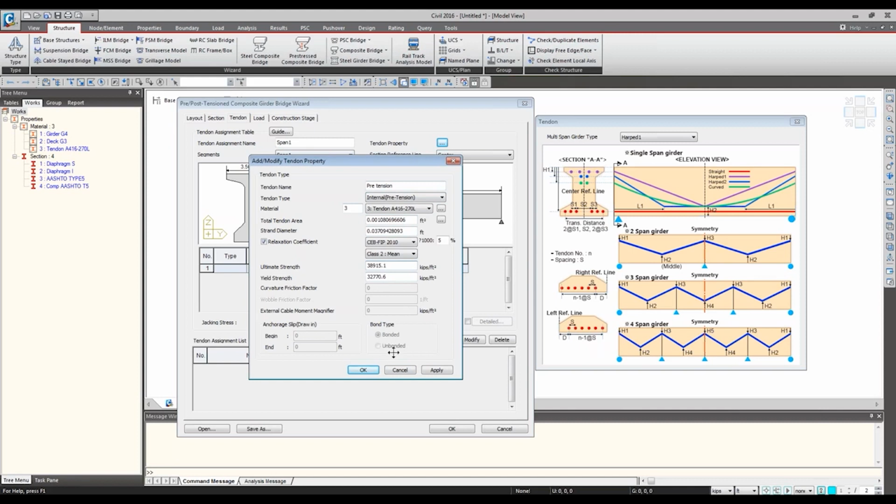Some of the questions I received in the past are such as, according to your agency regulation, you have to disregard the unbonded tendons. That way, you can simply define it unbonded and consider the different properties that come with the unbonded types. Or if you completely have to neglect them, you can simply not define them at all. You have all the flexibility.